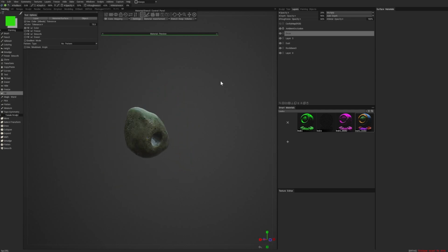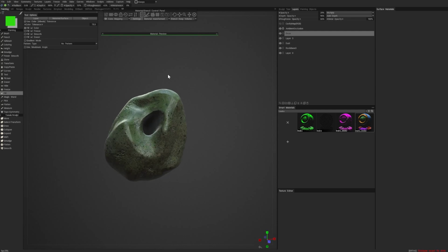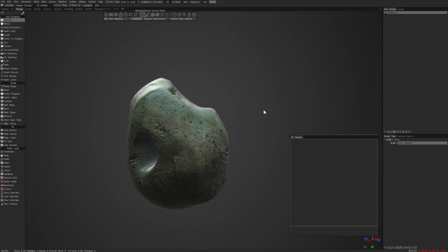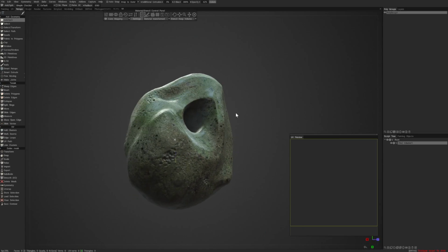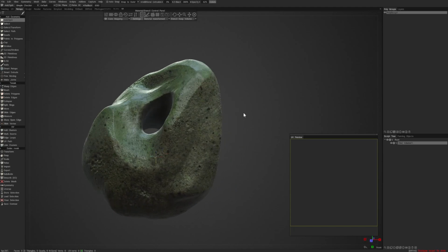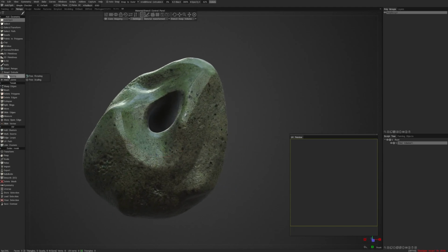All right, so anyways, say we're ready to export this thing. What we want to do at this point is go to, first actually we have to retopologize it. So to do that, we're going to go to Retopo, and now this is still a sculpt. This is a very dense 5 million poly sculpt. We want to make a lower poly approximation of this mesh. So I'm going to go in with my sculpt tools or my retopology tools, and I'll make this poly group basically the name of my final object.